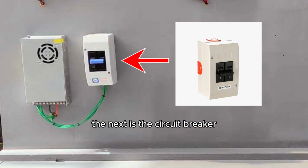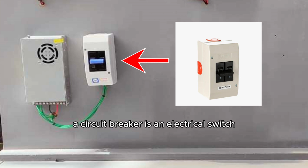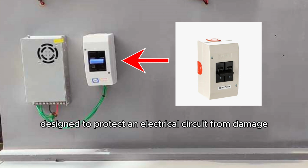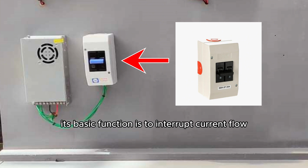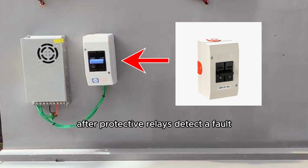The next is the circuit breaker. A circuit breaker is an electrical switch designed to protect an electrical circuit from damage caused by overcurrent, overload, or short circuit. Its basic function is to interrupt current flow after protective relays detect a fault.